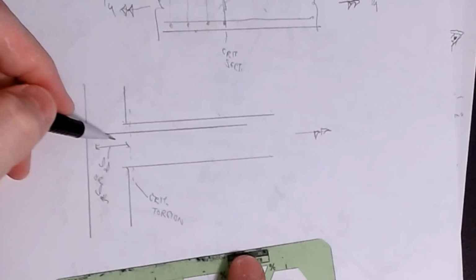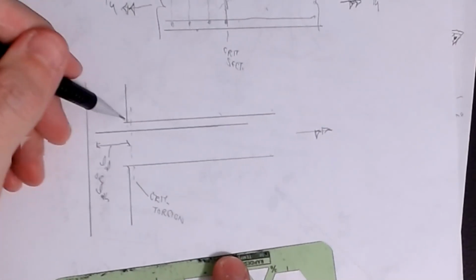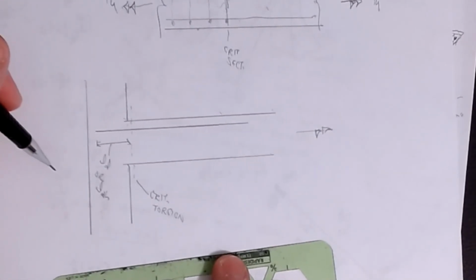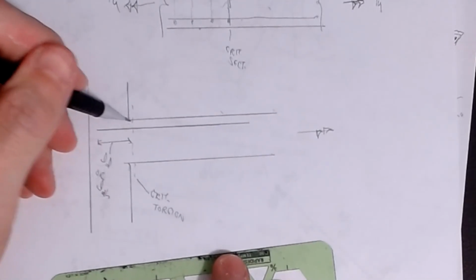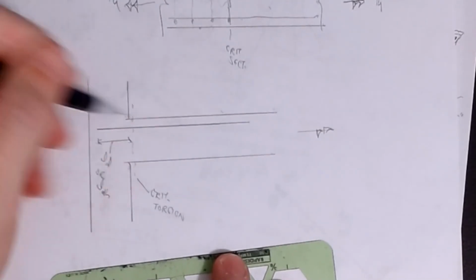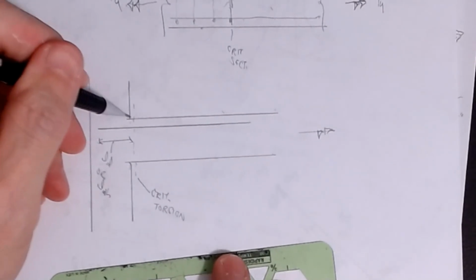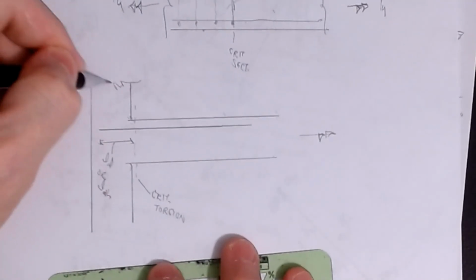And so if you're trying to anchor a number 8 or a number 9 bar and this is 30 inches, that becomes a real challenge trying to get this tied into a column. So that's one requirement we have to keep our eyes on, getting that development on both sides, because I need fy for torsion in the longitudinal bars here. So that's another issue.